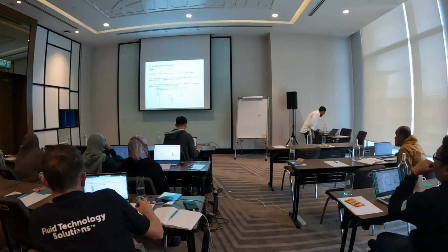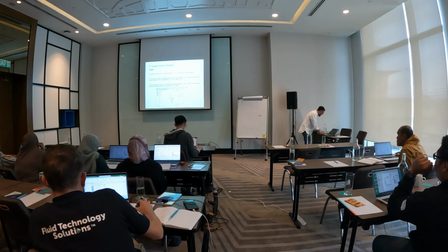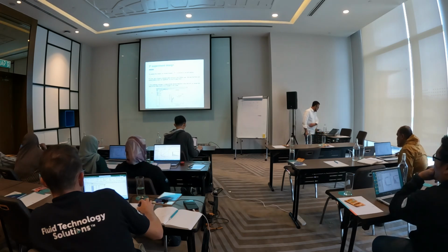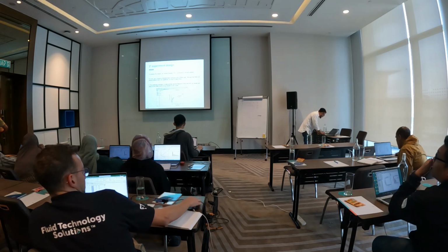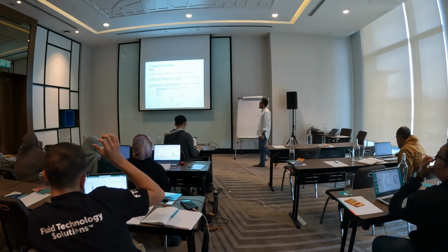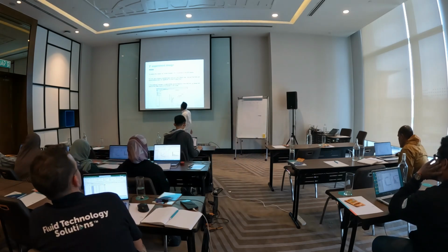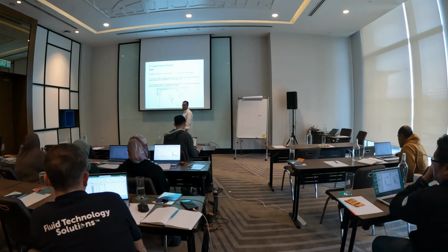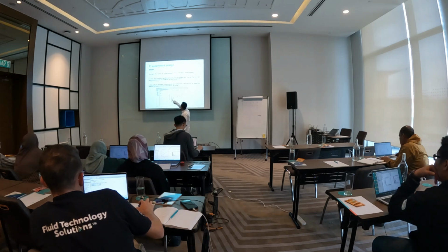Analyze the results. Choose R1 conversion on your left sidebar. So for now, let's choose the transformation and go to the effects tab. From there you can see, you can select the factors that do not fall into the half normal plot line, the red line. So you can select this factor A, B, C, AB, BC, ABC.